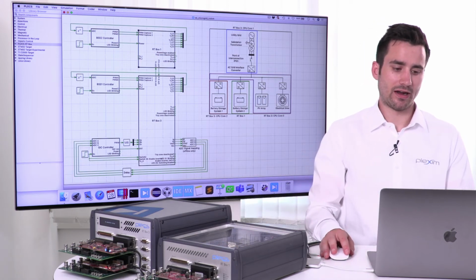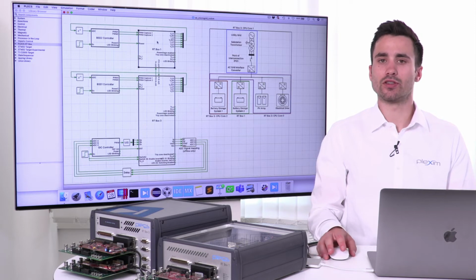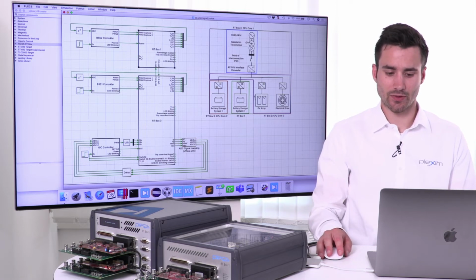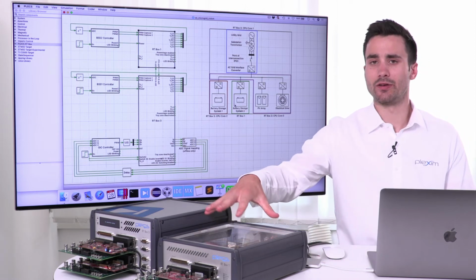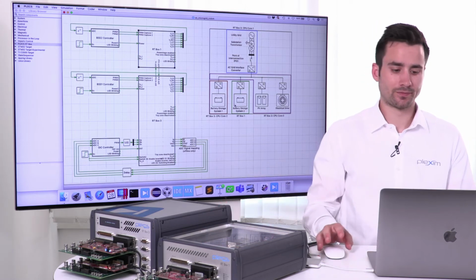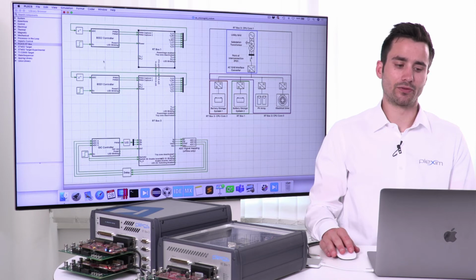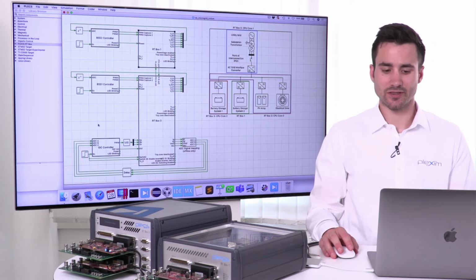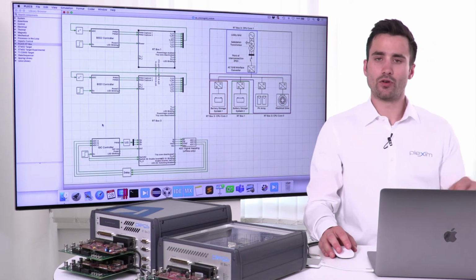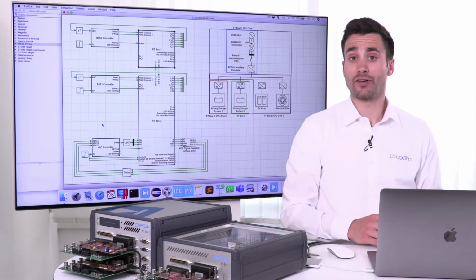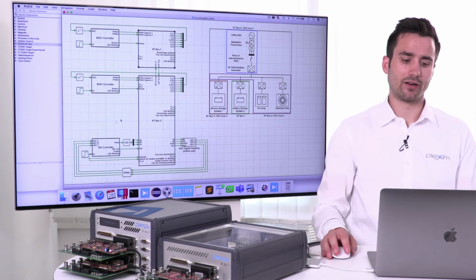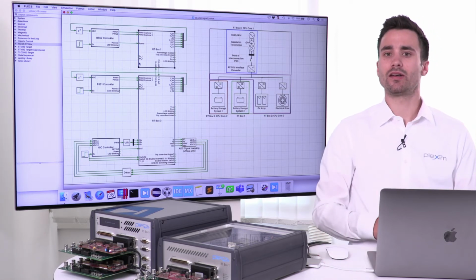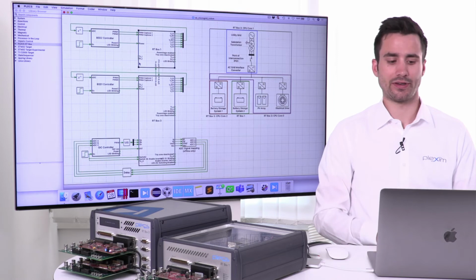So for example, everything that is included here in this Rtbox 1 subsystem, so the model of a battery storage system, will then later be executed in real time here on the Rtbox. And the same thing is then true for the remaining 4 subsystems. A good point or another advantage of this representation is that you can already identify here on this root schematic level which information is exchanged between the different hardware targets.